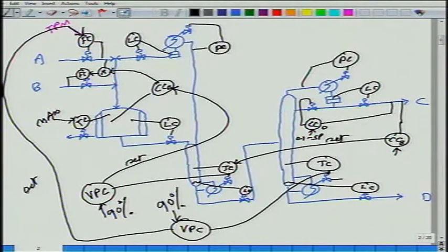So there is a back off in boil up in the stripper, there is a back off in boil up in the column. You would have wanted to operate at 100% boil up in the stripper, 100% boil up in the column. However, because it is important to ensure that too much B does not leak out the stripper, and that too much C does not leak down the bottoms in the column, in this control scheme I need to move the boil ups to ensure too much B does not leak out and to ensure that too much C does not leak out. Because I need to move the boil up, I have to give some margin.